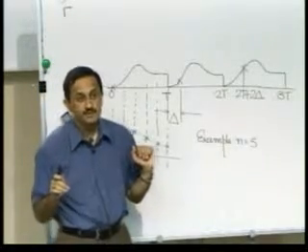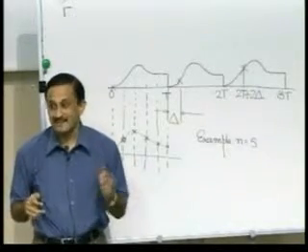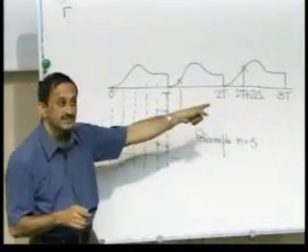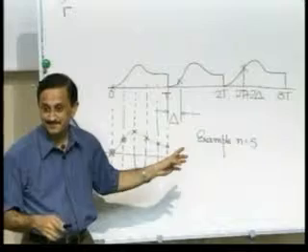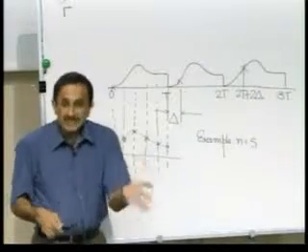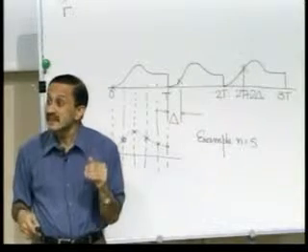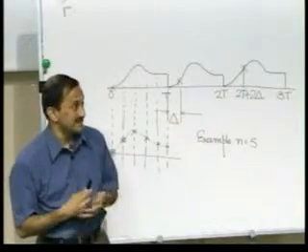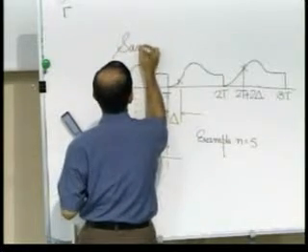Now, what am I doing effectively here? Effectively, I am using aliasing. What have I done? I have taken the original waveform, which is at a much higher frequency. I have undersampled it, that means sampled it at well below the Nyquist rate, right? And I have reconstructed what looks like the original waveform. That is what aliasing means, what looks like the original waveform from its samples. So, here aliasing has actually served a useful purpose for me, and this principle is the principle of what is called the sampling oscilloscope.